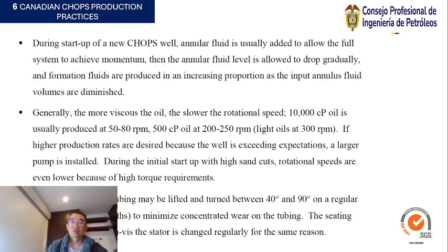Then the annular fluid level is allowed to drop gradually, and formation fluids are produced in an increasing proportion as the input annular fluid volumes are diminished.